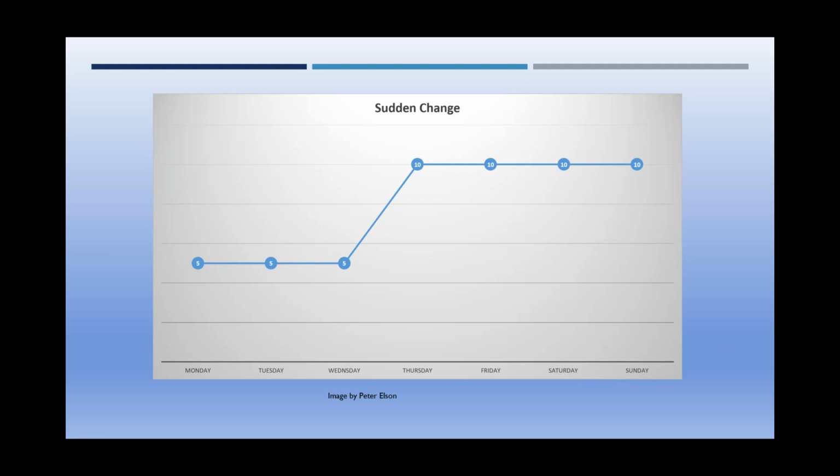And of course, if you find a sudden change, you really want to go and check your community to find out what's happening. Has somebody been doing some excavating? Is somebody trying to install a new curb stop that you're not aware of? In fact, that's, I think, one of the most common issues: somebody breaking a line or attempting to tap into a line. My view is that if anybody's digging a hole anywhere in your community, you really should be out there to make sure they're not hitting one of your water lines. Again, that's another good reason to make sure you've got all your isolation valves located so that you can isolate a leak quickly and have it repaired.